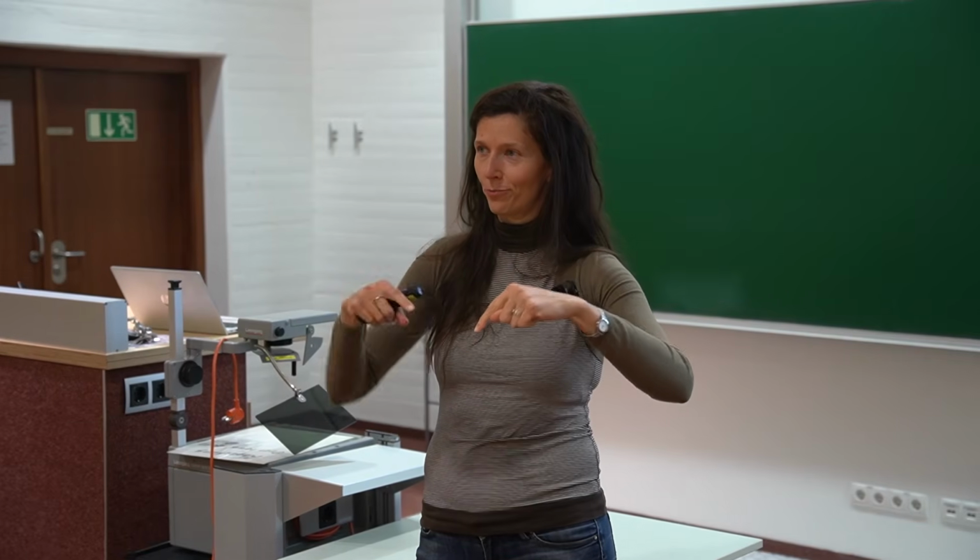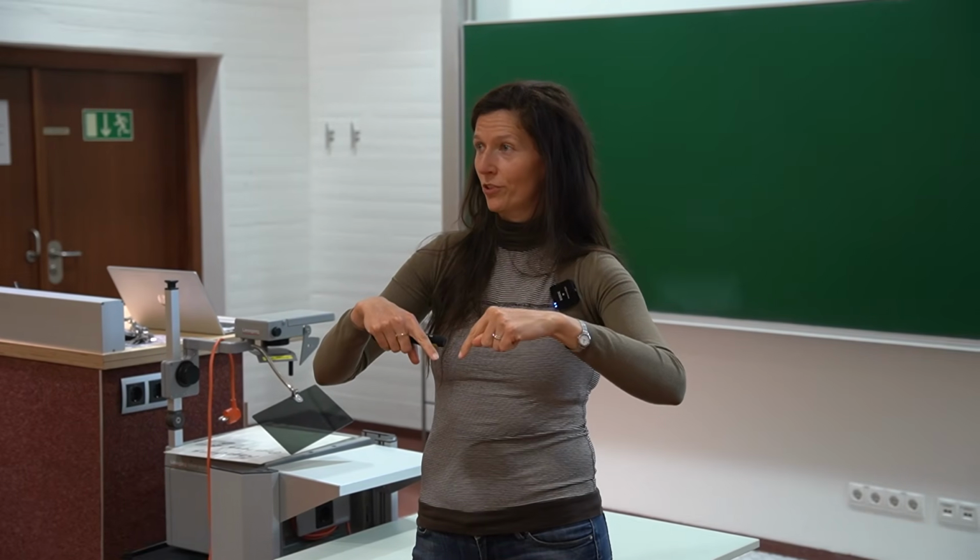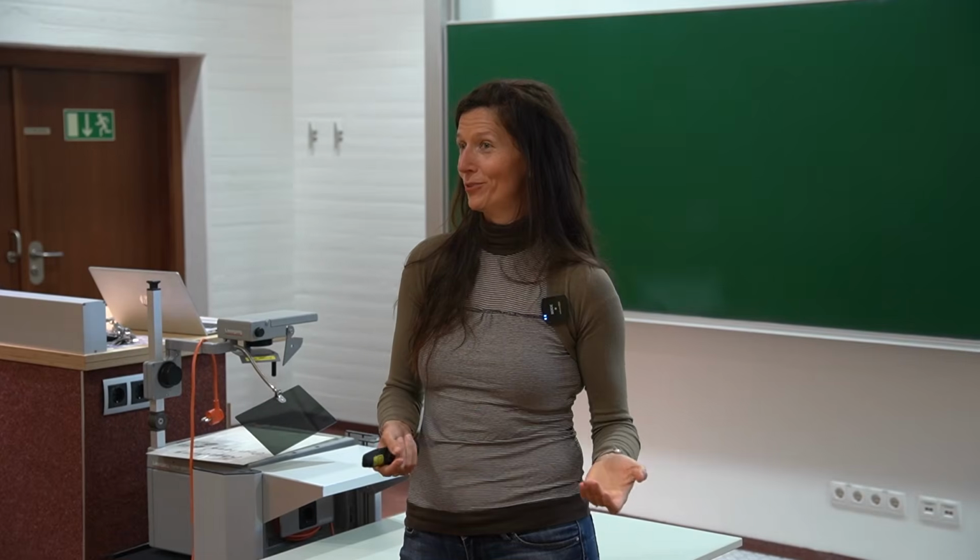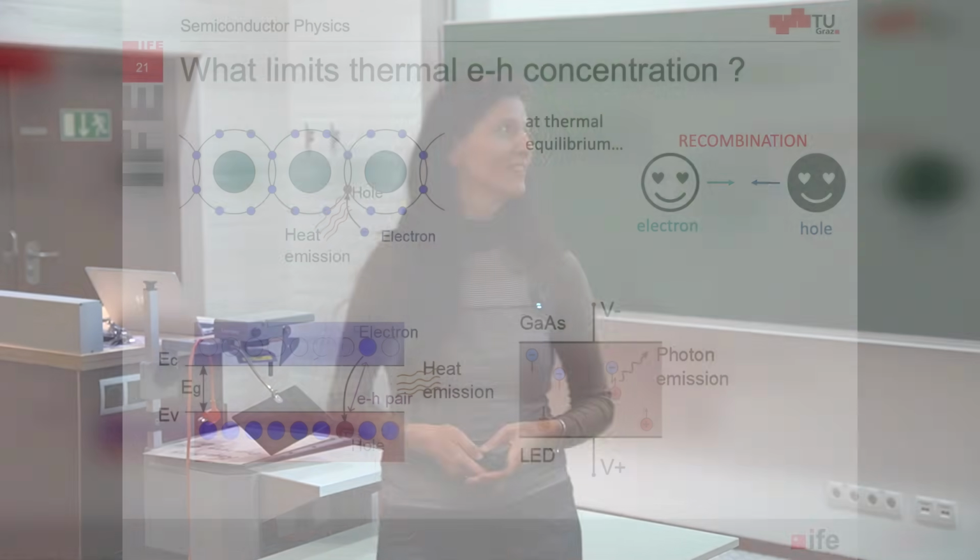What we sometimes have as a tricky problem in the lab, if we work with integrated circuits in a ceramic package, we can open the cover of the package to see what is on the chip. We can also place probes in order to contact specific pads in the chip. But if it's illuminated, it will not behave exactly the same as in the dark condition, because we have extra generation of charge carriers. So we have to put it in a dark place.